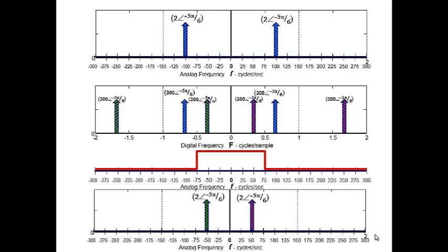So that's how we check. Right off the bat, as soon as I know it aliases, I know the frequency is going to change. It's moving. So then we can answer, where does it alias to? We can predict that. We have an equation for that.